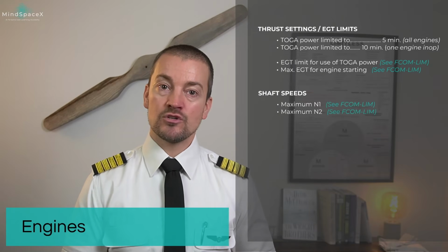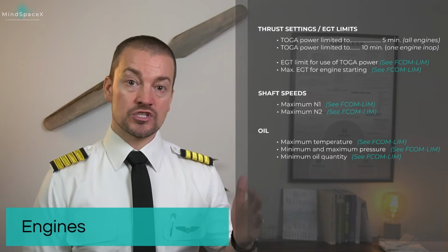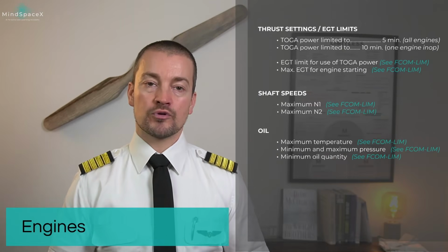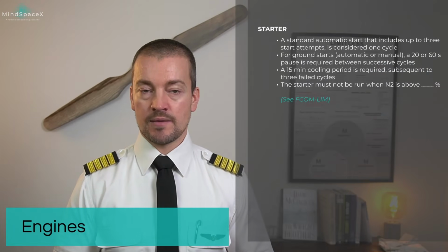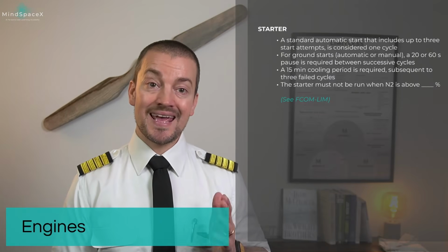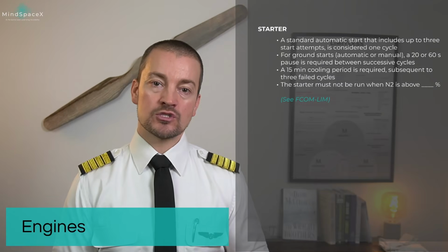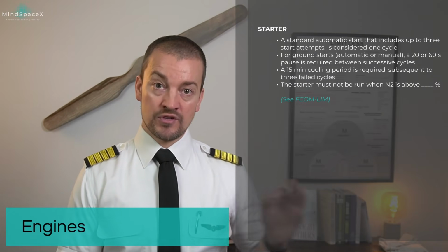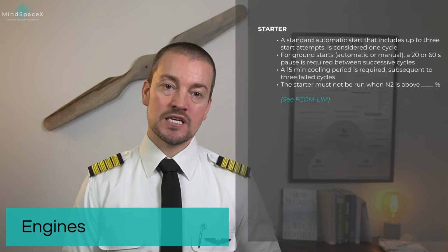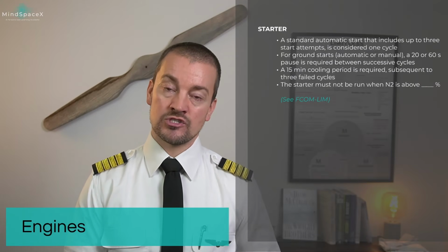Maximum N1 and N2 speeds, as well as oil limitations for temperature, pressure, and quantity can all be found in your appropriate FCOM limitation chapter. For the engines, there are limitations to the air starter motor, not as strict as the one on the electrical starter motor for the APU, but this is still a limitation that needs to be obeyed if you have to perform, for example, a manual engine start.